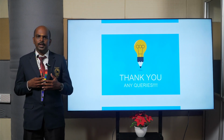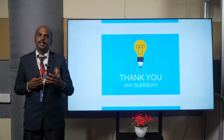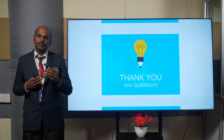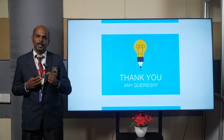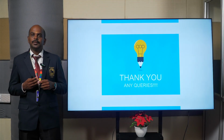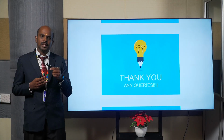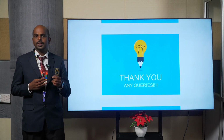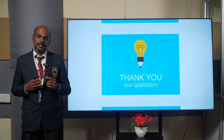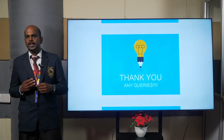Suppose we want our device to act as a voltage regulator. A PN junction diode will conduct only a small amount in reverse bias, in microamperes. To increase conduction in reverse bias, in a Zener diode we increase the doping slightly. So in reverse also a current conduction is produced due to the doping configuration, plus the minority carriers. That happens at one stage, when you increase the doping and the applied voltage.